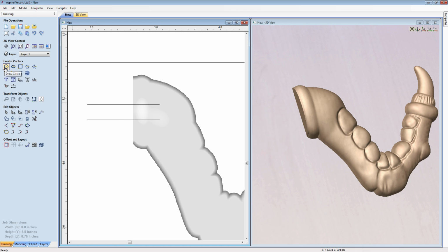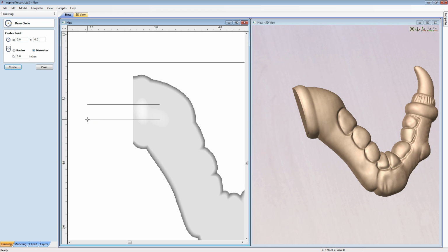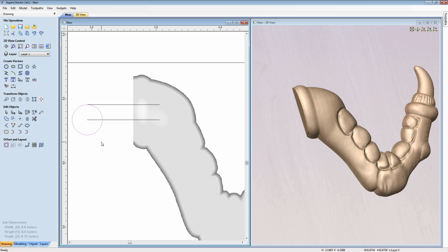Now I'm going to click Draw Circle. I'm going to snap to this endpoint and snap to this endpoint. Right mouse click to accept that. Hit N on the keyboard to go back into node editing. And what we want this to be is basically half the size, but I'm going to remove the 2 bottom halves there, but this is still too wide.